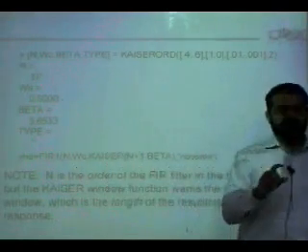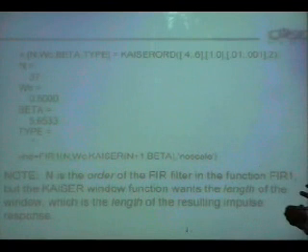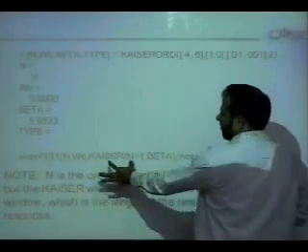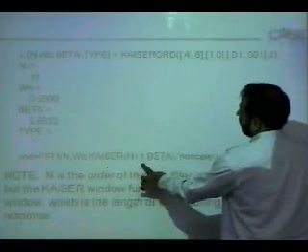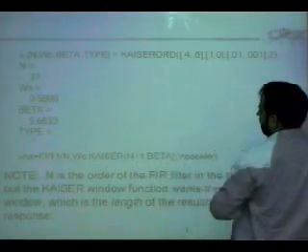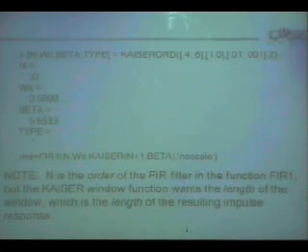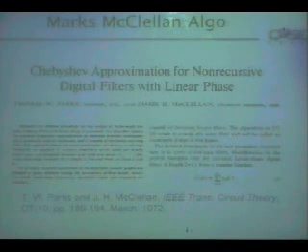With the MATLAB function FIR1, you have the option to use Kaiser window, Hamming window, Hanning window, Blackman window, all these windows by specifying that here. Here is n plus 1 and beta, and you can just read through these functions, but preferably you need not really do this, because the MATLAB toolbox is a better way of designing a filter.